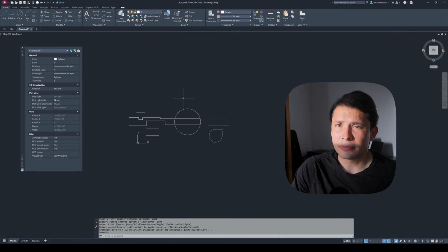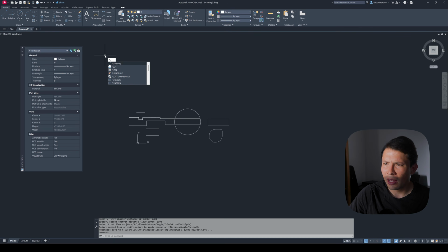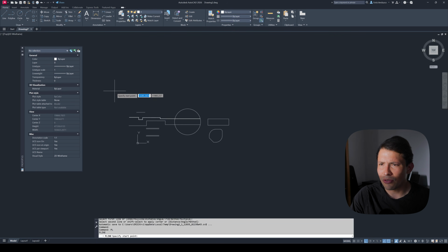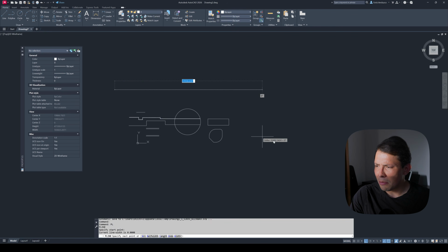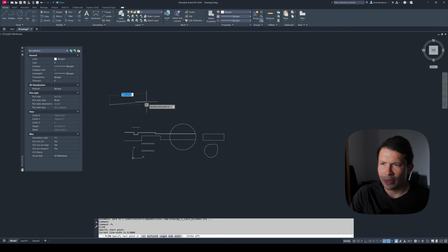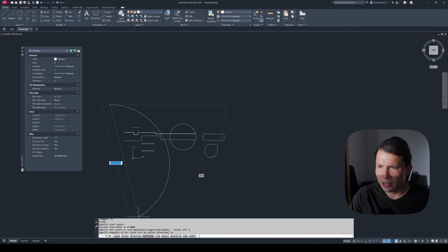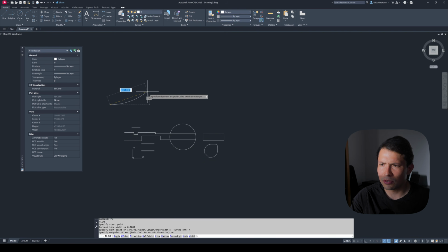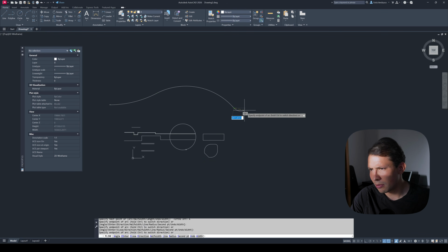And for doing that, I'm gonna click on a polyline. Again, the shortcut is PL. And then I'm gonna start drafting something. So I'm gonna deactivate my ortho command. For deactivating the ortho command, shortcut is F8. And with F8, deactivate allows you to go anywhere. And then instead of going on straight lines, I'm gonna click here on arc. So arc gives you the option to start drafting with an arc. And it's gonna be something like this. And then it's gonna go this way,